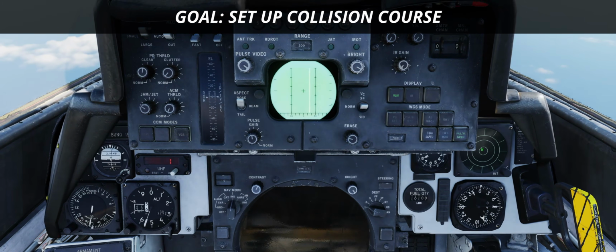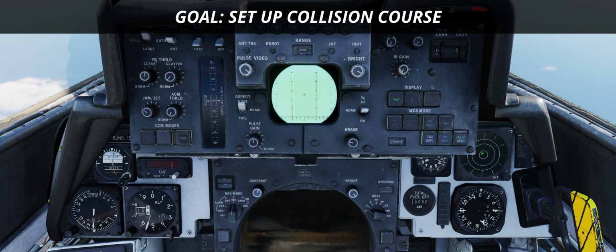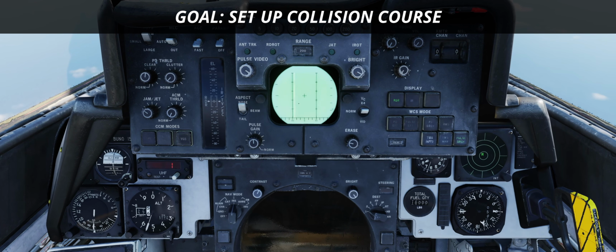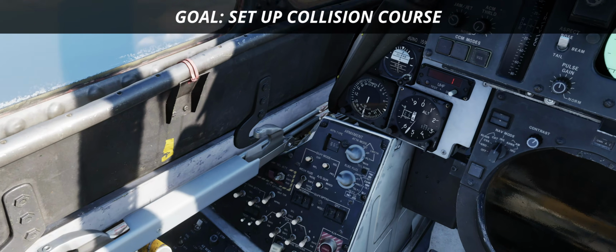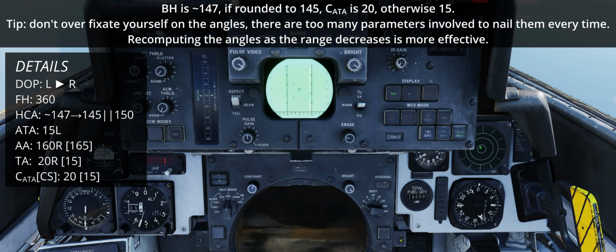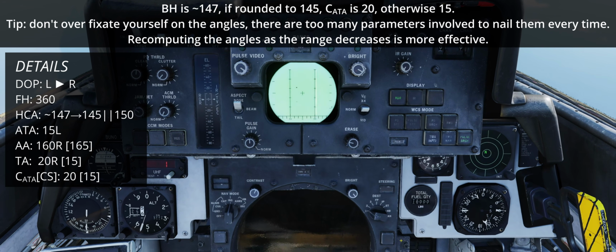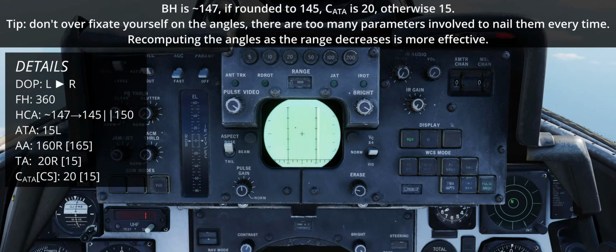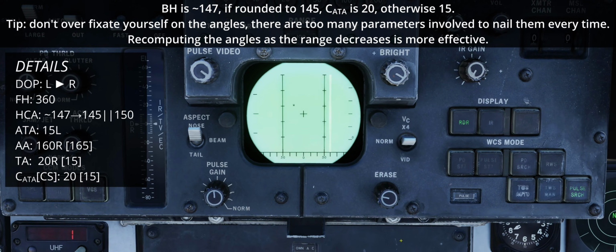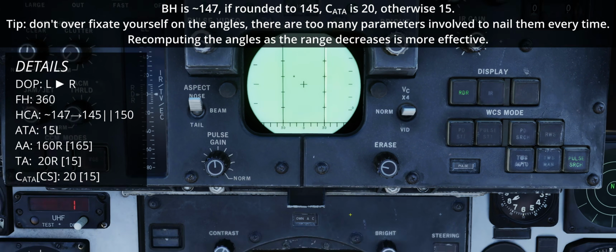Let's speed up time a bit until we get something on the radar. There we go, 60-something miles. I see basically no drift, ATA 15 left, DOP or direction of passage is left to right. Let's compute a heading cross angle, target aspect and aspect angle. To do this we check the BDHI, paying attention to the parallax effect.